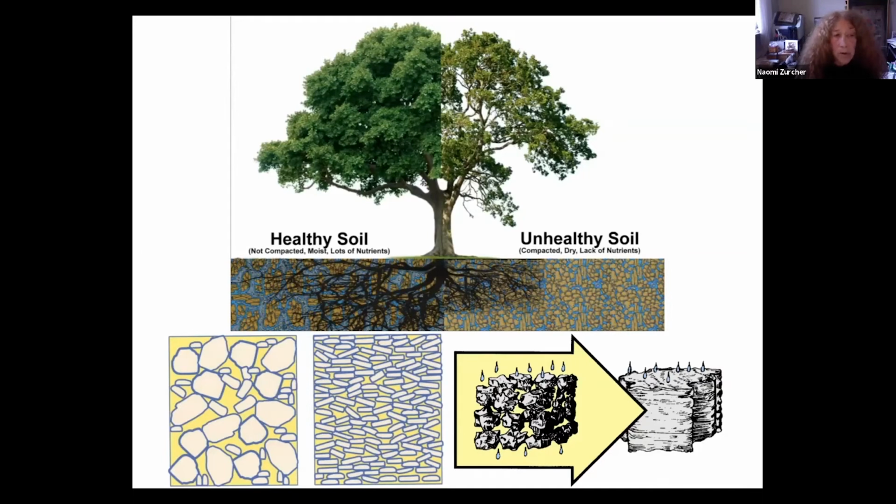There are a number of alternative paving options, but the extent of substrate compaction will greatly affect soil attributes. What needs to inform our paving choice should be human usage combined with the greatest possibility for unimpeded tree root growth. The alternative surfaces in production today, along with their tree and soil advantages and disadvantages, are as follows.